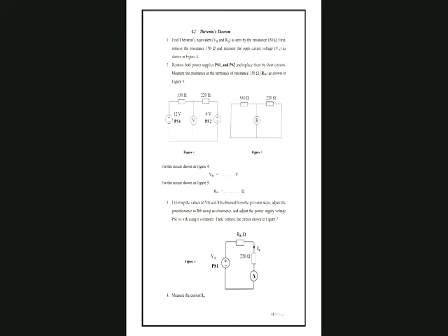I'll just show you what we have done. We have noted down that we got 10 volts of V Thevenin and 131.4 ohms. We set V Thevenin to 10 volts using the multimeter, and this is nothing but your 131.4 ohms, and instead of 220 I take 150.